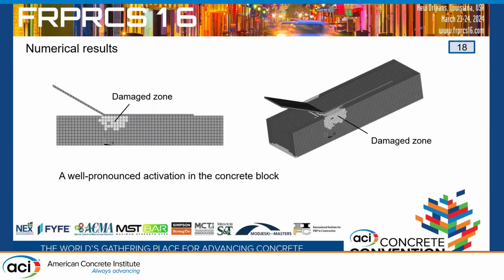One interesting outcome of using damage mechanics is that you can see the distribution and the evolution of the distribution of damage in the concrete substrate. We are using damage mechanics here only to model concrete behavior, and therefore we have results for damage only for the concrete substrate. In gray you can see damage zones.